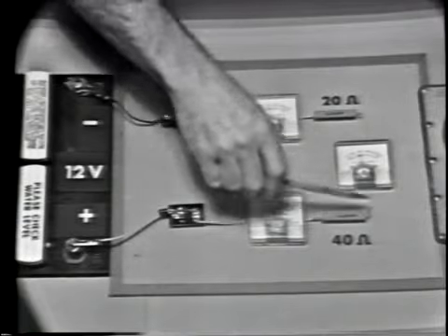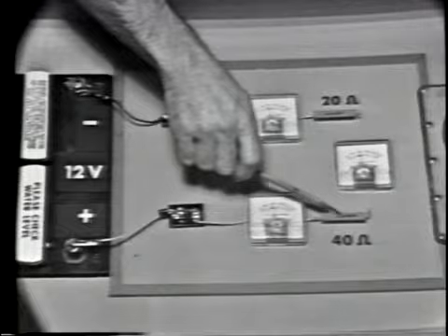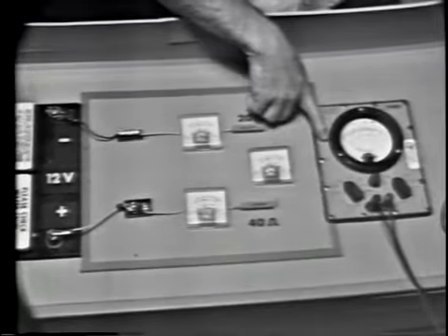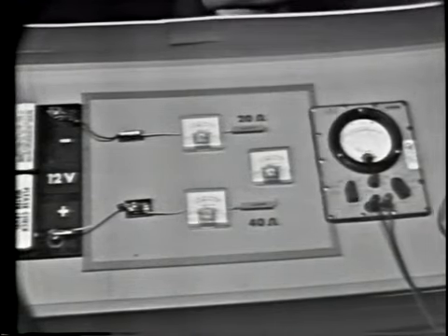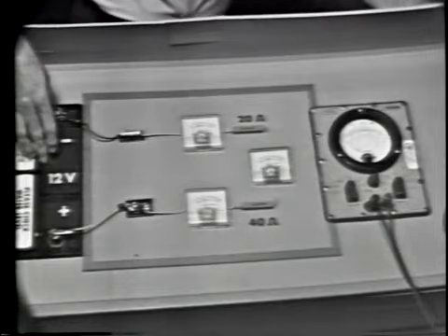According to Kirchhoff's voltage law, the applied voltage will be dropped around each closed loop. In this circuit, this means that the applied voltage will be divided among these two resistors, and the sum of these voltage drops will equal the applied voltage. Let's use the PSM6 and check this out. We'll set the PSM6 to the DCV function, and we'll use a range of 50 since the applied voltage is 12 volts, so we're being safe.